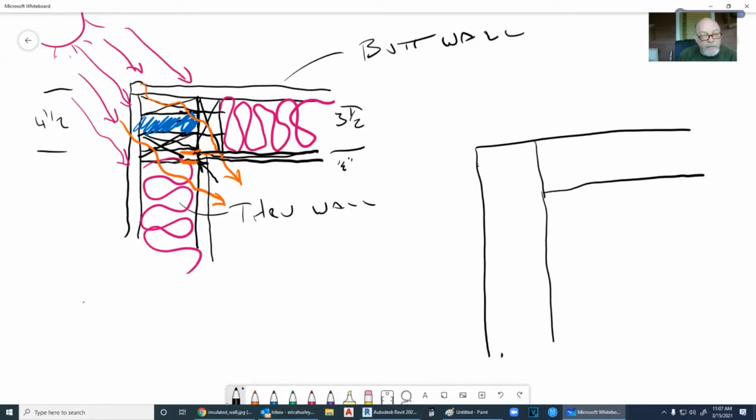So people would put plywood in here to increase this out so that I didn't have to worry about which piece of drywall to put on first. If you did it that way, you'd have 1 inch. What's that? If you put the one on the left first, you'd have a whole inch. Then when you butt the other drywall, you'd still have 3/4. No, you'd have a whole inch either way. No, 1 inch take away 1/2 is 1/2. No, I'm saying if you put the one you've drawn vertically in there first, you've got the whole inch. Yeah.